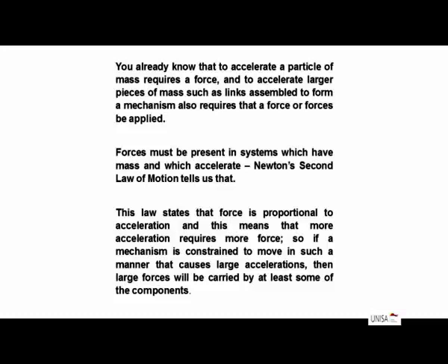Newton's second law of motion tells us that. This law states that force is proportional to acceleration, and this means that more acceleration requires more force. So if a mechanism is constrained to move in such a manner that causes large accelerations, then large forces will be carried by at least some of the components.